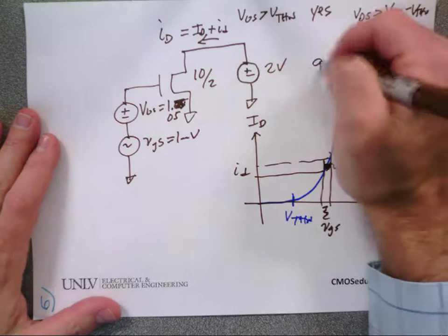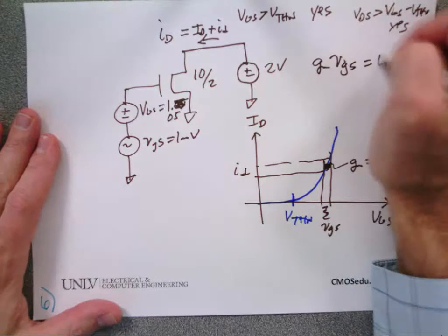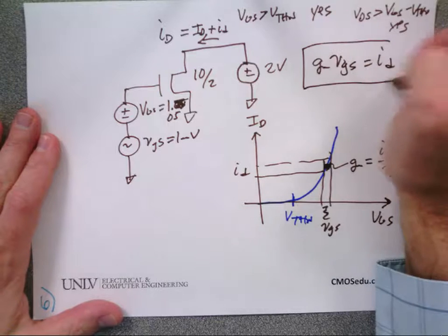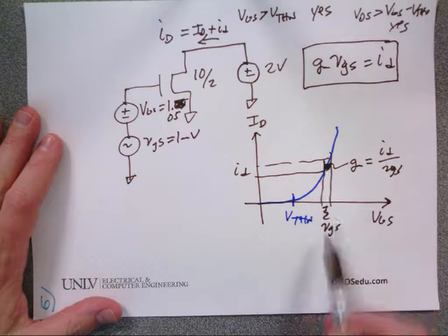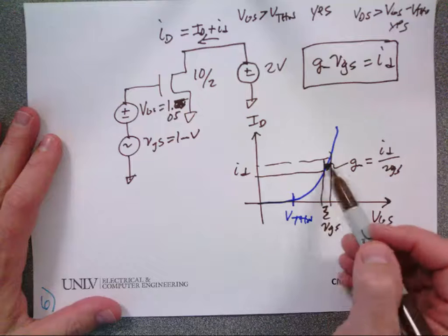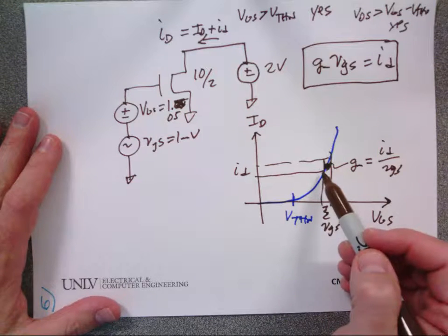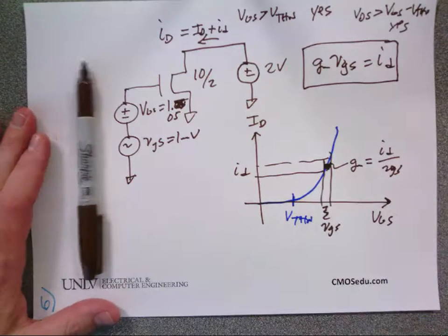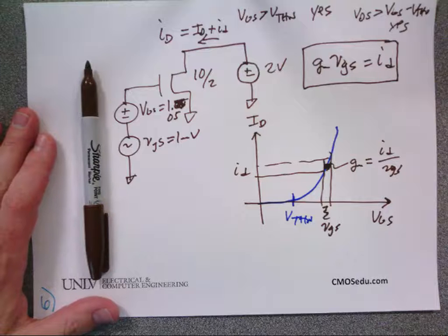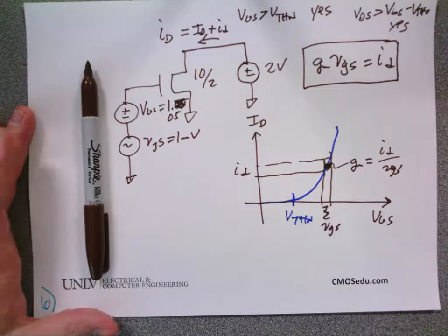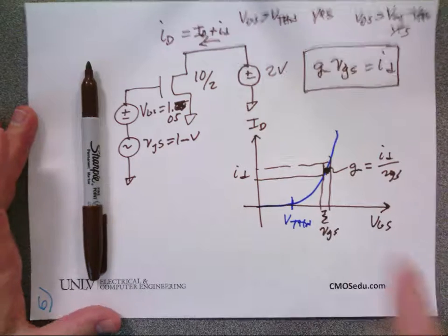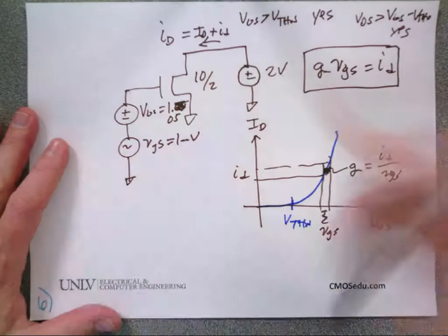And so this is the equation that everybody always forgets, but we'll use it hundreds of times in this class. I'm going to derive it, but notice I'm assuming that the DC VGS is large compared to the AC. In other words, I'm assuming that I've turned the valve on enough that when I wiggle it, I'm not wiggling it enough to shut it off. I'm wiggling it so that it's small compared to the amount it's on. Everybody follow that?